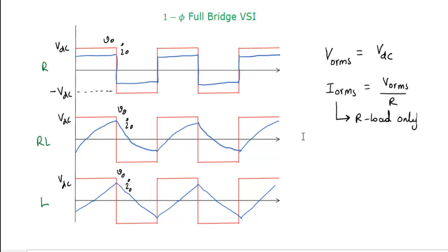Now here, as we discussed in the half-bridge inverter, the waveform is also a square waveform, a perfect square waveform, where each half cycle lasts exactly 180 degrees. In that case percentage THD will be similar, no difference at all, because percentage THD and distortion factor always depend on the shape of the waveform.